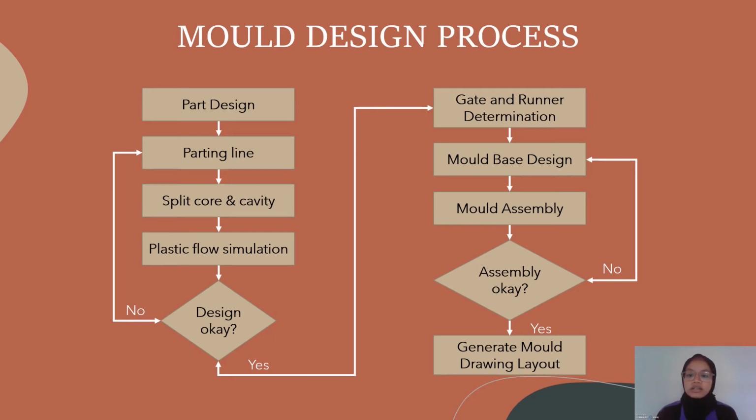The detail of the design of the part used by SolidWorks must include functional purposes, material selection, and economic justification. For example, the cost estimation of the product and the quantity of production can be incorporated. The second stage of the mold design process involves the determination of the parting line, core, and cavity, gating, and runner type, and the approximate injection mechanism.